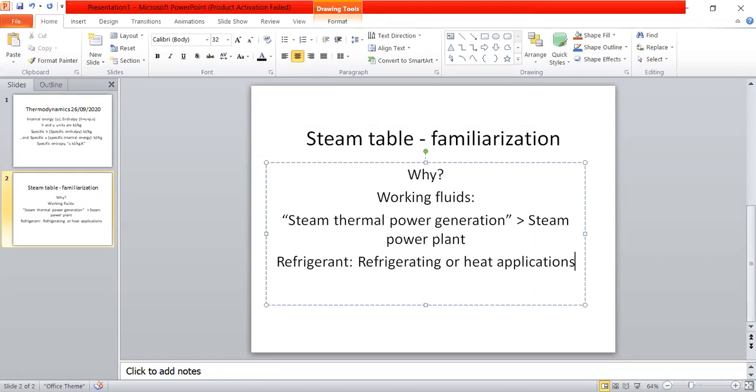So consider all the components in the refrigeration circuit, starting from any point. If you start from the evaporator: compressor, condenser, and then through the metering device, the expansion valve, back to the evaporator and to the compression again, and the cycle repeats. Through this cycle, the refrigerant passes not as a passenger, but as a really working fluid. Understand? So there are other types of working fluids as well.